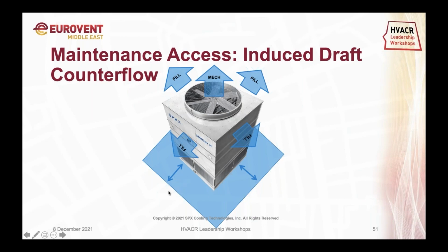First, airflow, and second, any potential inspection, replacement, maintenance for the internal components of that cooling tower, and also inspection for the mechanical parts: gearbox, motor, fan, etc.